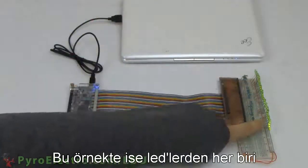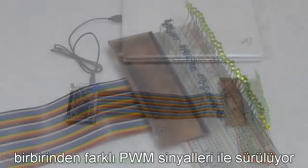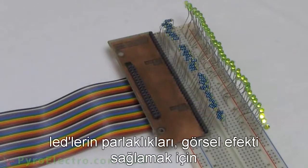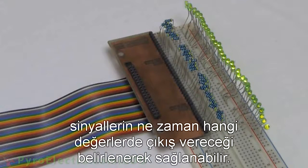As another example, each of these LEDs is being output a unique PWM signal to make each one have a unique brightness. On top of that, the brightness level between the LEDs is constantly changing to create a neat visual effect. This can only be achieved by keeping track of time to know which signals should be outputting what value.